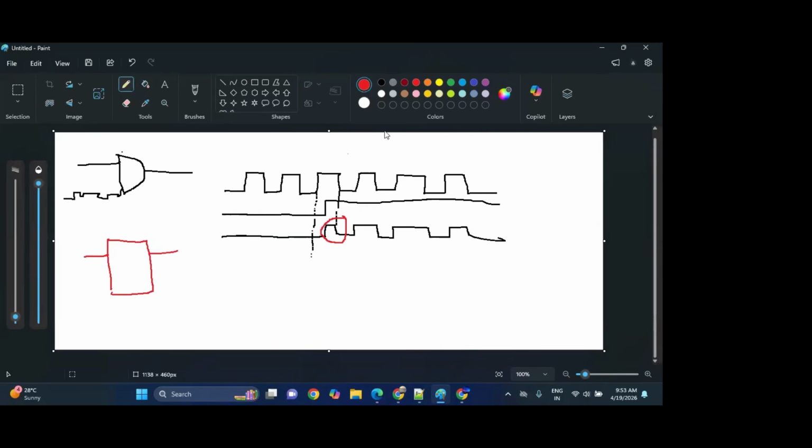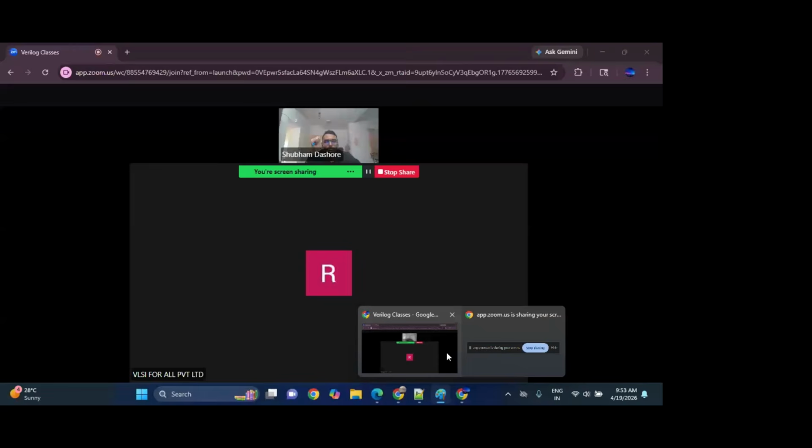Okay. You know about body effect. What is the impact of body effect on the leakage power and delay? Body effect means we are biasing the body of the MOSFET by applying some positive voltage or negative voltage at the body of the MOSFET.